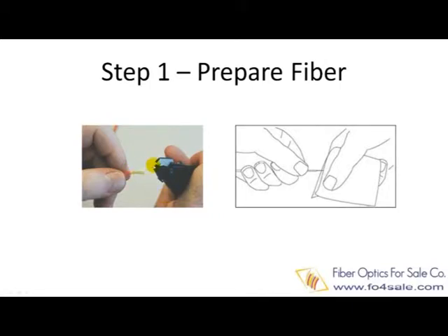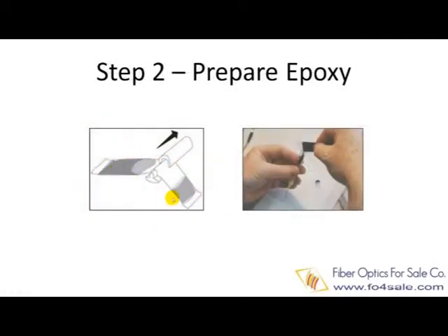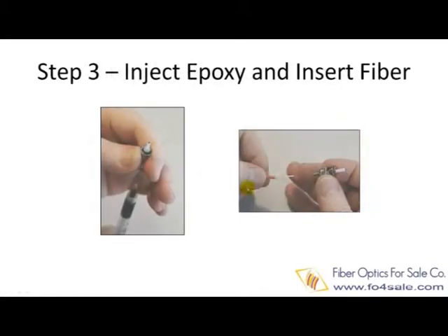The SC connector also continues to trend toward quick termination fiber connectors. Now, such connectors typically use a combination of no polish crimp bond construction to speed up the termination time to as little as 60 seconds per connector. These quick termination connectors drop the time consuming step of epoxy bonding the fiber to the connector by using a crimp-on system, somewhat similar to coax cable connectors. The main difference is that the fragile glass fiber absolutely must not be deformed during the crimping process, or it may fracture or break. In addition, some of the new connector implementations now use a pre-terminated connector arrangement.